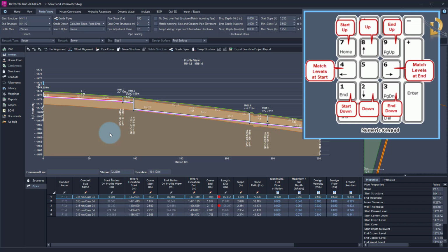And also it depends which keyboard shortcut you use, but it should be much easier because you don't need to think about, should I use Control, should I use Alt? No, it's very simple. Let me show you. So I will select this path and the following path, and then I can use Control 3 to move it down, Control 1, start, Control 9, up, Control 7, down.